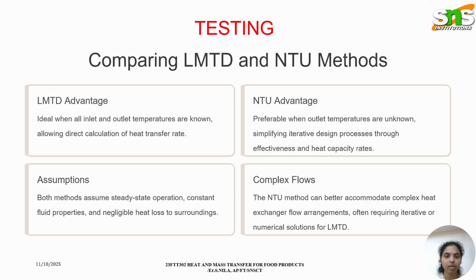Now the comparison of LMTD and NTU methods. So what are the advantages of LMTD and what are the advantages of NTU? LMTD is ideal when all inlet and outlet temperatures are known, allowing direct calculation of heat transfer rate, while NTU is preferable when outlet temperatures are unknown, simplifying iterative design processes through effectiveness and heat capacity rates.